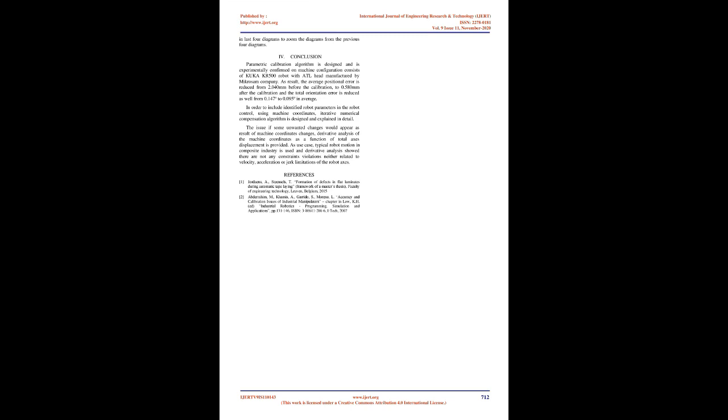The same 297 poses are used calling the iterative numerical compensation algorithm, described in the previous section, in order to obtain another G-code of compensated machine coordinates, concerned with the same path the tool should follow. Tool poses refer to the pose space, and Euclidean distances used to generate such uniformly distributed poses along the tool path refer to the physical 3D space where the robot motion is done. That does not mean each of the robot axes would perform uniform displacement.